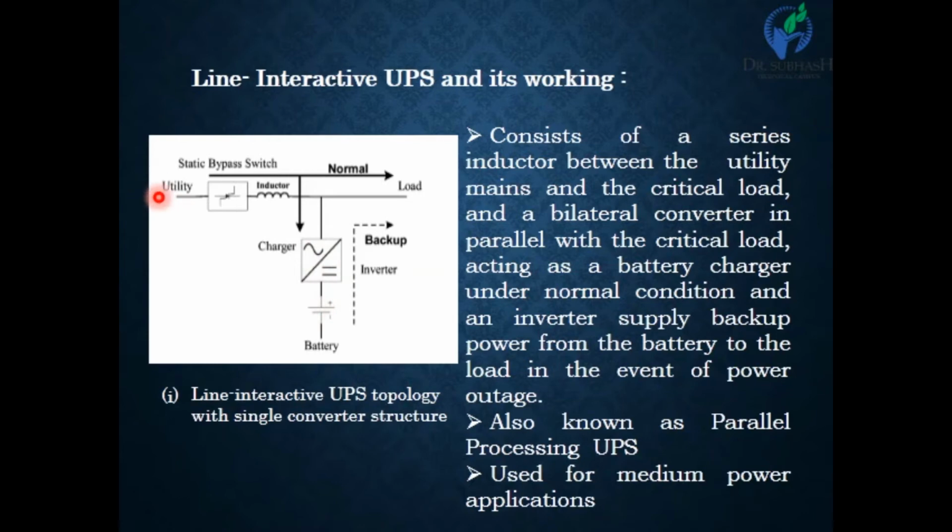So this AC power is converted into DC via this converter. When the utility system is cut down and power is not received from there, this converter works as an inverter, not a rectifier. So the battery will provide DC, and this inverter converts DC into AC and provides the power to the load.